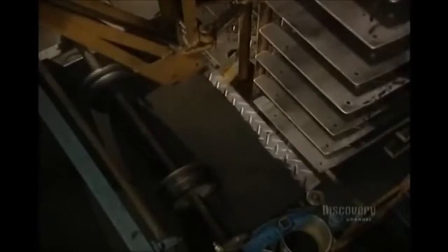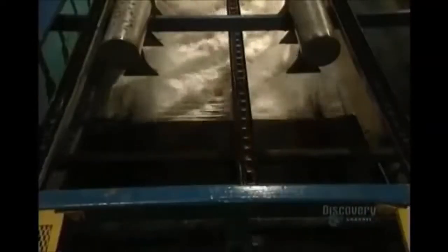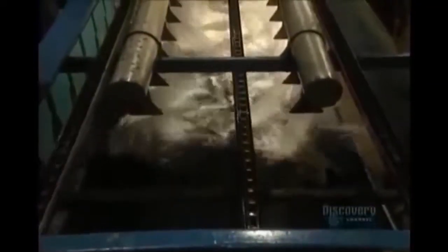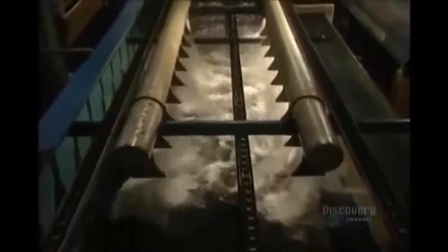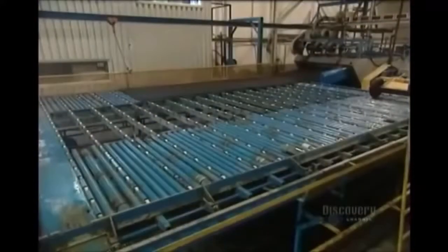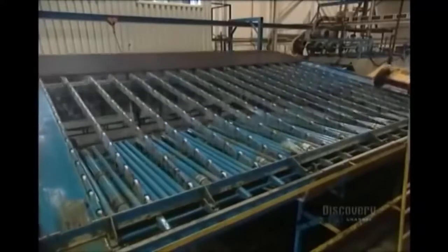Here's the mat press. The powder has to be cooked at a very high temperature for about 30 minutes. Cooking time depends on the product being made. The cooked mat goes through the unmolding unit before being sent off to cool. The rubber mats are still extremely hot. They're cooled with jets of water for a period of several minutes. The cooled mats can now be sent to the next department.